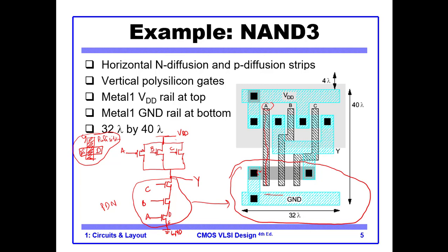On one side of this polysilicon there is the source of a transistor, and on the other side there is the drain of a transistor. Transistor number A. You see that the source is shorted with the ground through this contact. And what is this? This is the contact for substrate. This is the substrate tap, the fourth terminal which is connected to the ground.